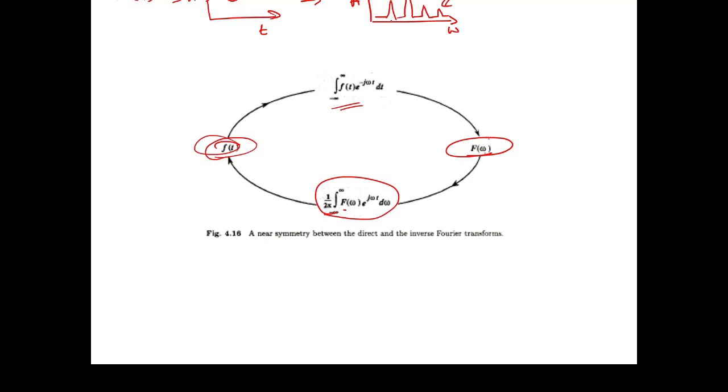Say for example, at 50 hertz, at 100 hertz, I'm just giving you an example, okay? 150, say 200. Now say for example, you got this signal and you can see a 50 hertz component. You might have some corrugation over here. You don't know whether these corrugations, which are basically noise, are 50 hertz noise or not.